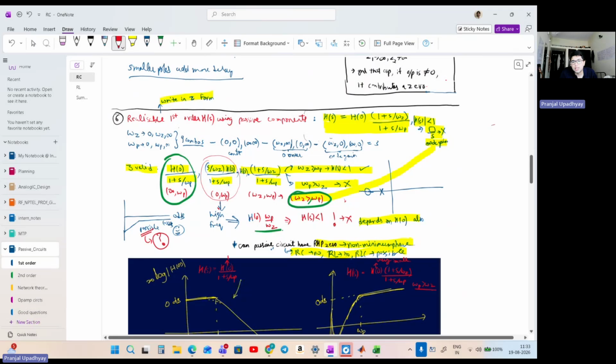It will look like just s by s, right? Because this is at zero, here it is also at zero. So clearly, this transfer function is a constant, and thus basically it does not have any dynamics of a first order system, and thus we have to remove it.